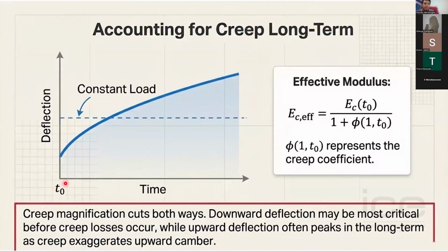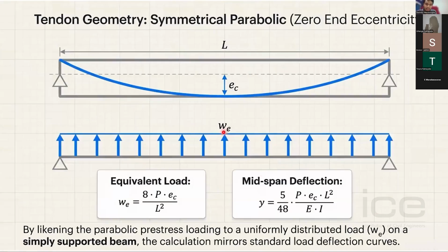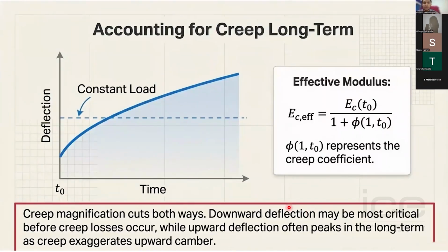And one more thing to notice is that the E value: if you are calculating the instantaneous deflection at the initial stage, the E value as it is can be taken. And if you are calculating the long-term deflection, the elastic modulus will change because of the creep.